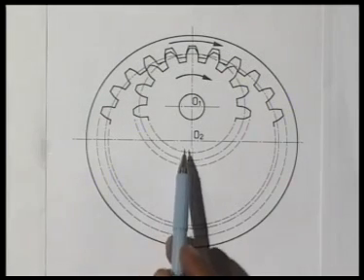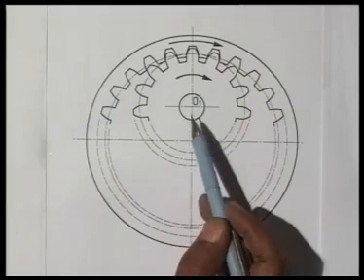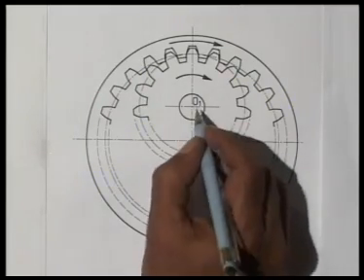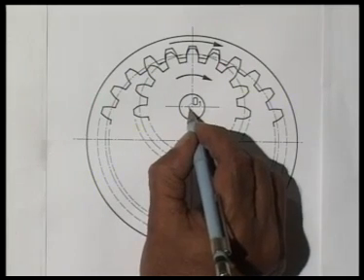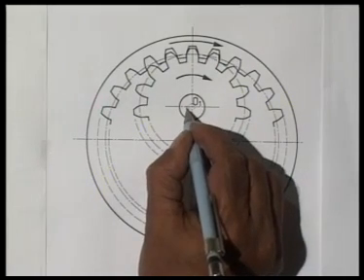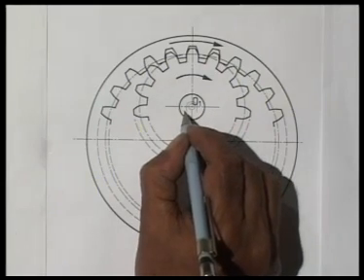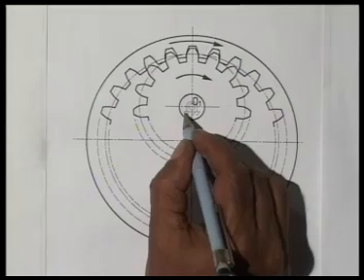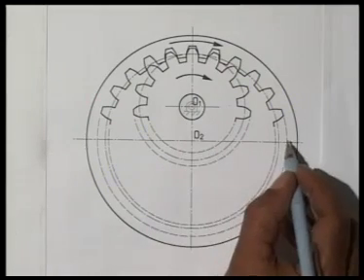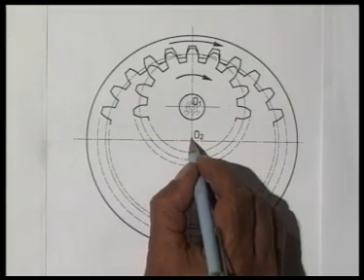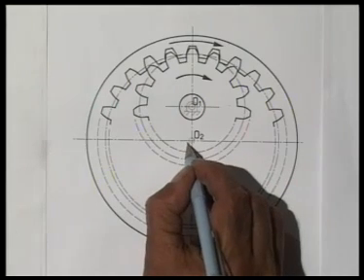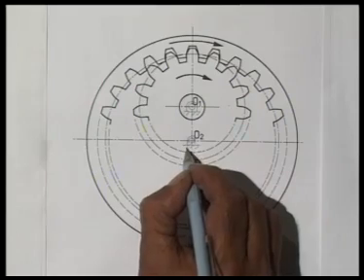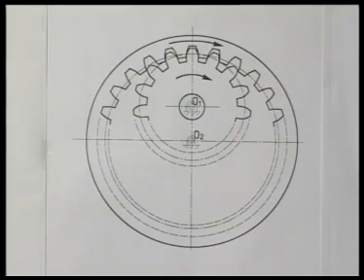This figure shows a pair of internal gearing. There are two shafts. There is a bearing between the frame of the machine and the shaft containing gear 1. There is a revolute pair here. This is gear number 2, which has a revolute pair with the fixed link. So this constitutes a 3-link mechanism.